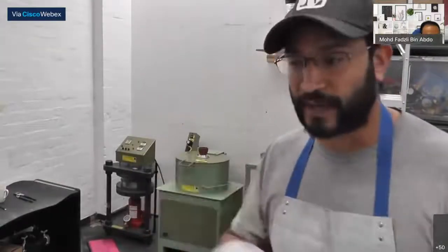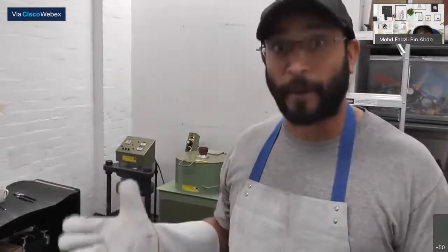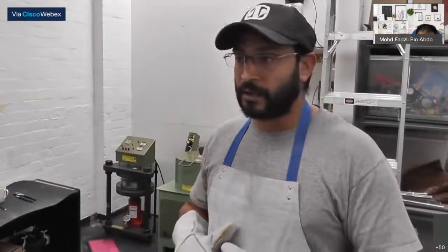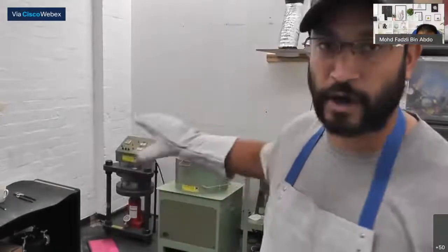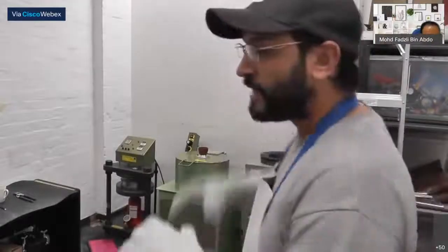I've been spinning some moulds for the last week or so. Nothing I can use or sell at the moment. They're just copies of existing figures that I've been moulding for learning: learning how to make moulds, learning how to spin them, learning how to dial the pressures in on the spin caster, the speed and all that sort of stuff, the temperature of the metal, how to pour those. Each of these ingots probably weighs maybe 5 kilos.